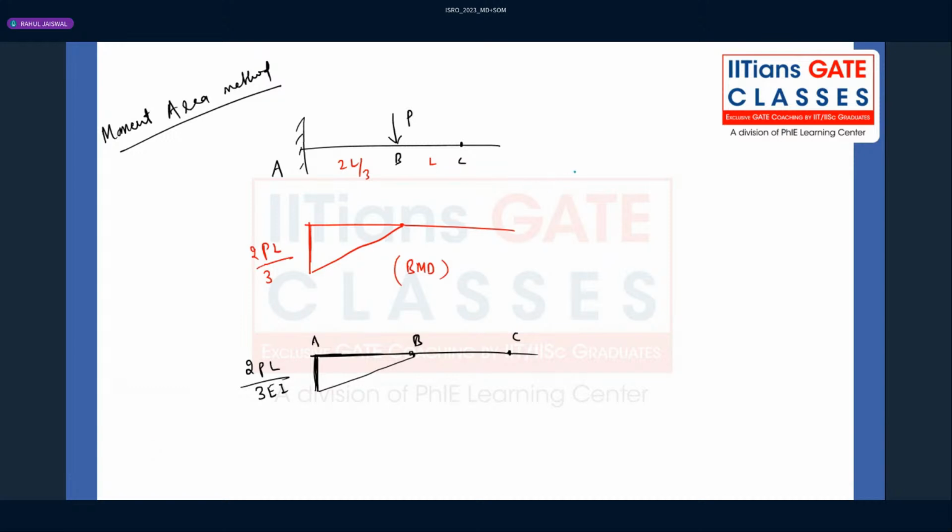When you see theorem number 2, by theorem number 2 you can write delta C equal to the moment of area, delta C with respect to A, right? Moment of area of the M by EI diagram between A and C about C. I'm not repeating the statement once again here, but if you want to calculate deflection at any particular point, you take two points on the elastic curve.